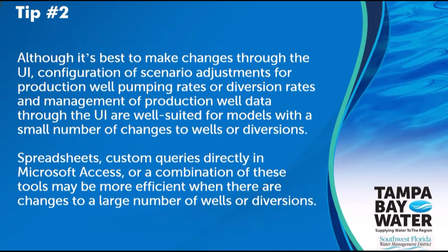Tip number 2. Although it's best to make changes through the user interface, configuration of scenario adjustments for production well pumping rates or diversion rates, and management of production well data through the user interface are well suited for models with a small number of changes to wells or diversions. Spreadsheets, custom queries directly in Microsoft Access, or a combination of these tools may be more efficient when there are changes to a large number of wells or diversions.